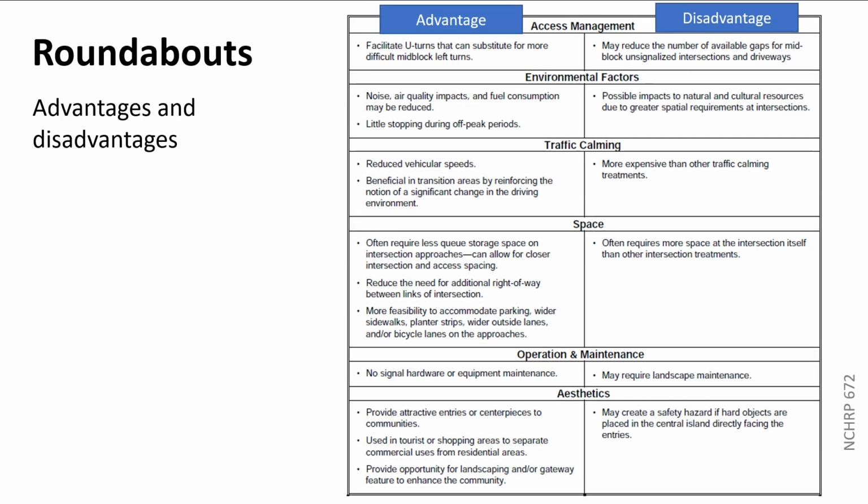Through that, what are some of the reasons we would want to use or not use roundabouts? So roundabouts are another tool in the toolbox. If we have an at-grade intersection, as a designer, at least when you're doing the scoping reports, you'll look through the options and decide what's my best option for this location. And it could be a two-way stop, a low volume, wide open space, plenty of sight distance. A two-way stop could be great, and that's all you need, and it's cheap. Right, those are cheap. Maybe it's a traffic signal, maybe it's a roundabout.